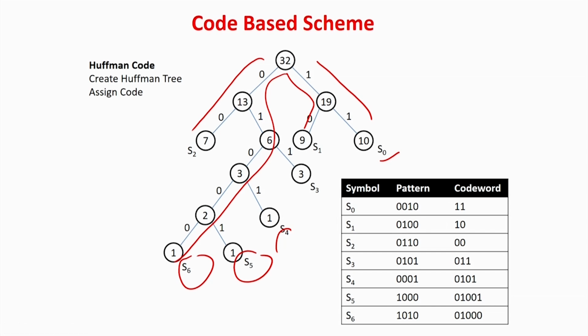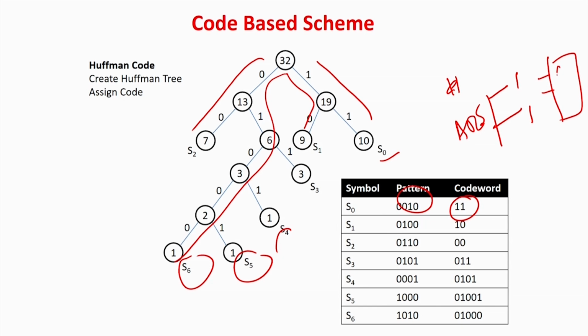But again of course, it is very important that when I get this as 1 1, the decompressor circuit should generate the pattern inside. So maybe 1 1 will go from the ATE. So the ATE will generate 1 1, 2 pins will be there, I am using them for the timing, and it will go to your CUT. So the CUT will be getting 1 1. Inside there should be a circuit for decompressing it. It will generate it as 0 0 1 0. So there should be a decoding circuitry for the Huffman codes, which is a very standard circuit you can study from any textbook. So in this case also 1 0 and 1 0 1 will be there.